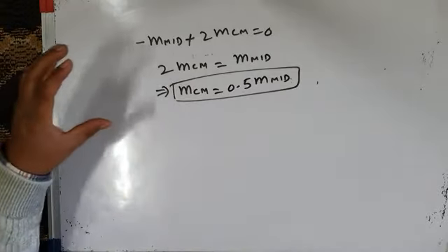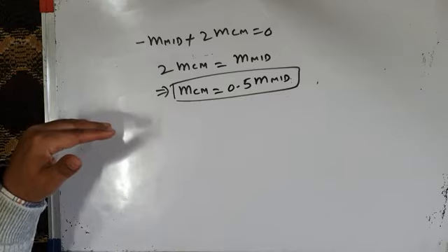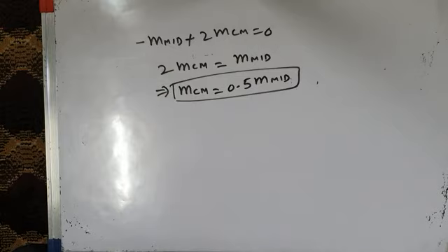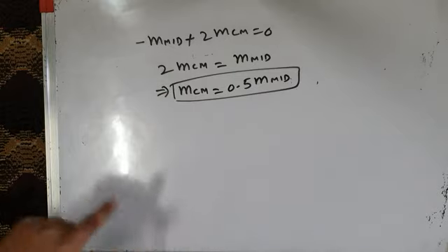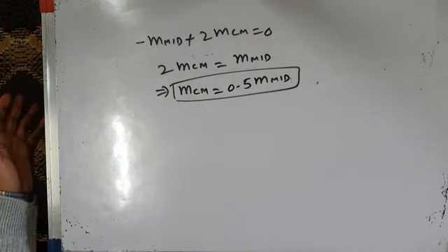Add that common mode signal to the three original sinusoidal modulating waves, M max, M min and M mid. That will give modified modulating waves, M max star, M min star and M mid star. Compare those three modulating waves with a high frequency triangular carrier wave, generate the control pulses for the 6 switches of the inverter, and you will get the same results as given by space vector PWM.